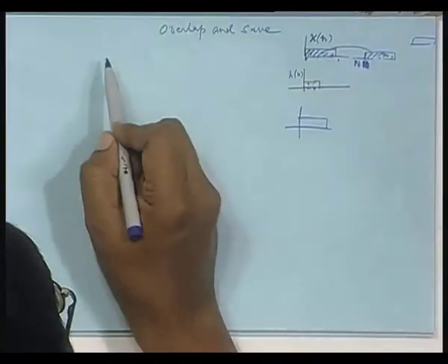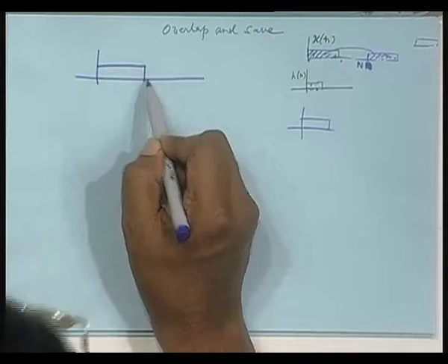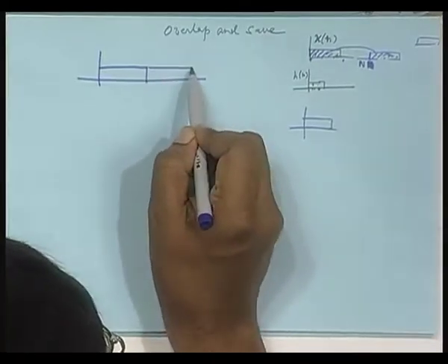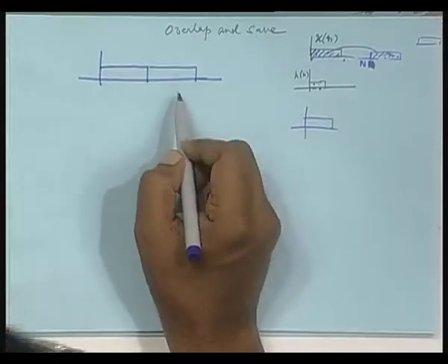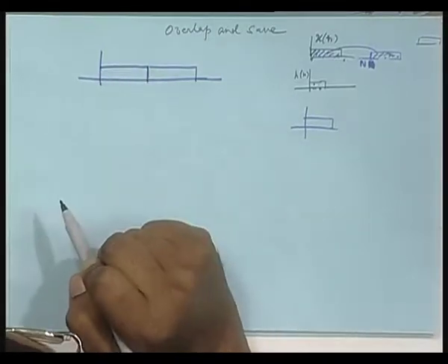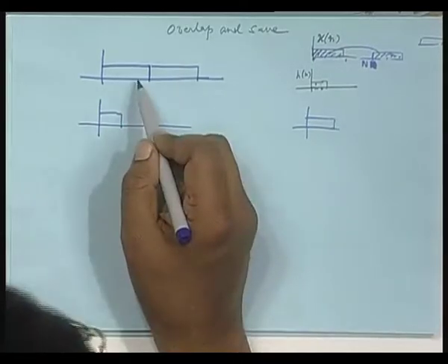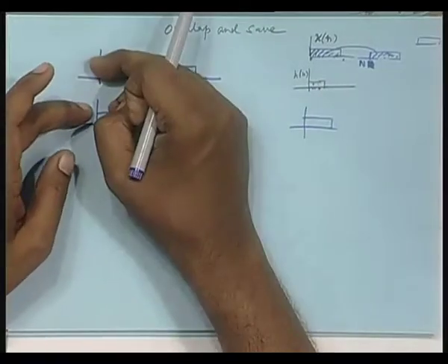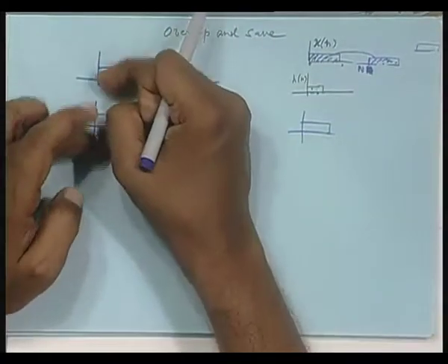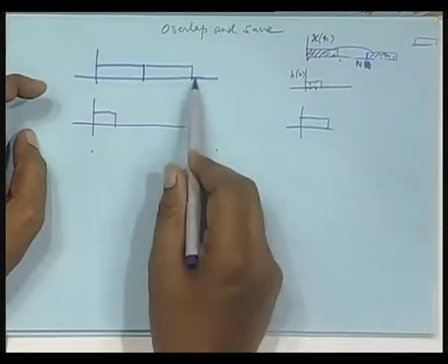Isn't it? Another important thing, and this is what books do not mention. These aspects are very surface level, and they missed out this point. Suppose this is data, this data I am segmenting like this, and there is one sequence I am convolving with. Fine, you know how to do linear convolution: reverse it, multiply sample wise, shift it again, multiply sample wise, shift it, go on doing it, you will get an output from here to some point to the right of this.